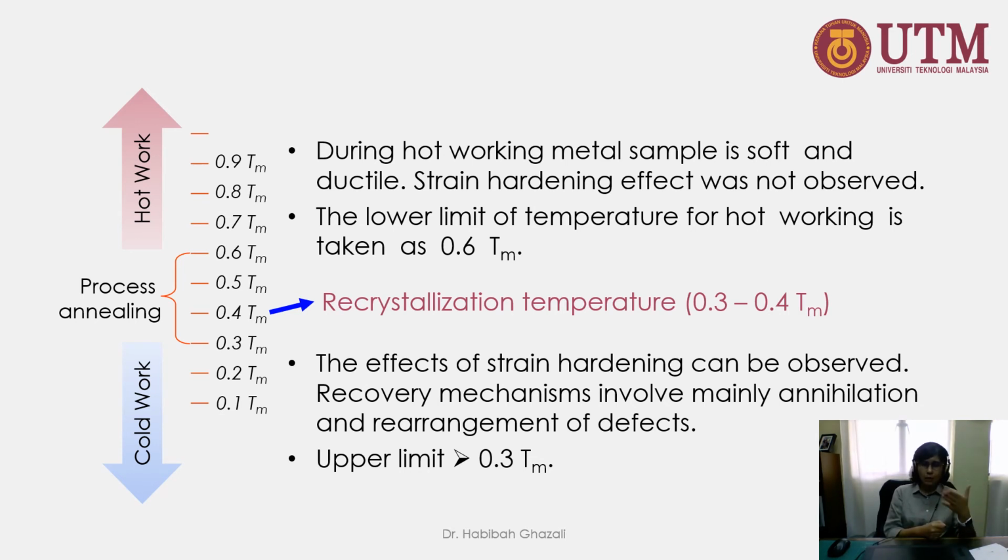So with cold working, materials will become harder and also will have higher strength, and at the same time, we know the ductility will be reduced. So what we can do, we do cold working to increase its hardness and strength, and at the same time, we reheat them or perform a heat treatment process in order for them to restore some of the ductility.